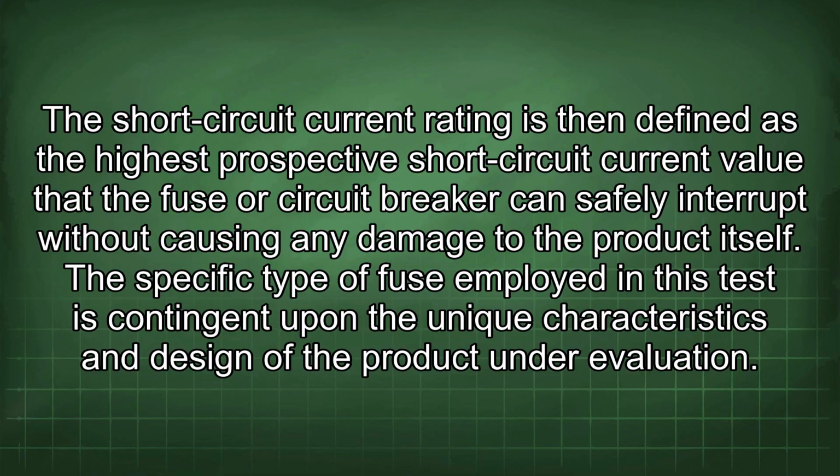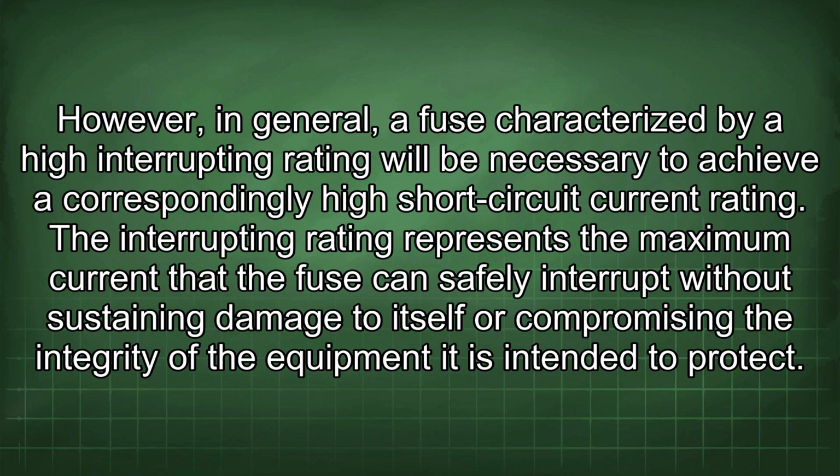The specific type of fuse employed in this test is contingent upon the unique characteristics and design of the product under evaluation. However, in general, a fuse characterized by a high interrupting rating will be necessary to achieve a correspondingly high short circuit current rating. The interrupting rating represents the maximum current that the fuse can safely interrupt without sustaining damage to itself or compromising the integrity of the equipment it is intended to protect.